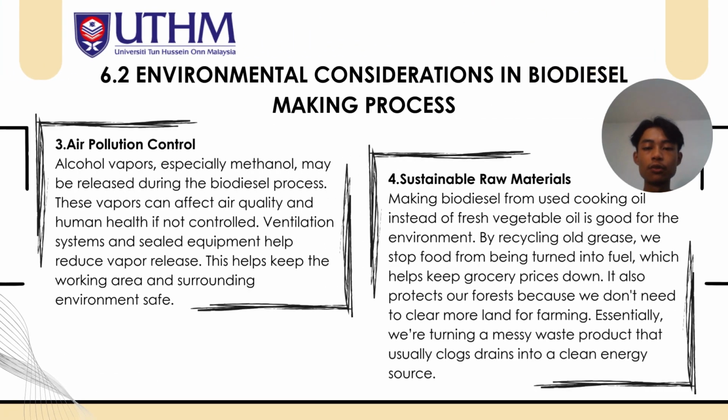Next, air pollution control. Alcohol vapors, especially methanol, may be released during the biodiesel process. These vapors can affect air quality and human health if not controlled. Proper ventilation systems and sealed equipment can help reduce the amount of vapor released. This helps keep the working area and surrounding environment safe.